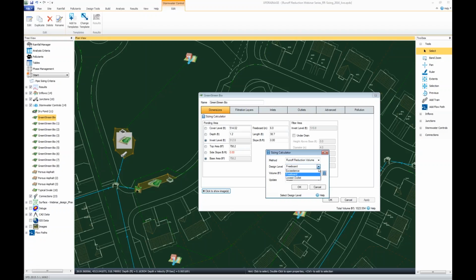One thing that I quite like is if you have outlets. In the real world, perhaps the freeboard isn't a constraint, but you have some sort of outfall weir. So it will find the lowest outfall, and it will size the volume under that. So you have a high flow bypass, and I can't occupy any stage level above that, so size just everything below my high flow bypass. And then, of course, when I get into my more major events, the bypass will work as expected, and I've sized for the more minor events. Okay, so we might just look at the freeboard for now.